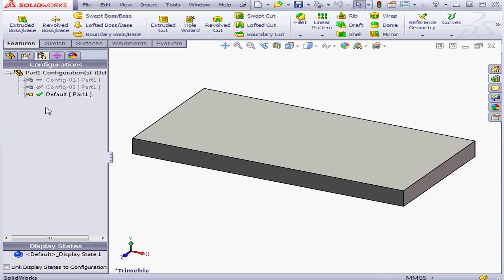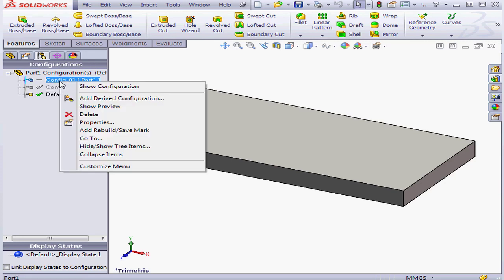So how this all works and what the point of it is this. When you generate the dataset and save, the file size increases. On the positive side, it's faster to switch between configurations when all the datasets are up to date. Of course, it's very noticeable and potentially cumbersome for big and complex designs. So what's new is that in this release of SOLIDWORKS, we have the option to flag the configuration with the Rebuilt Save mark. It gives you just a little more control.